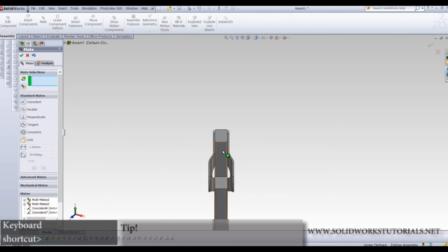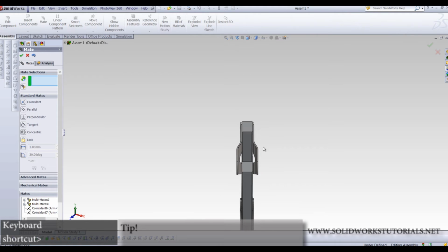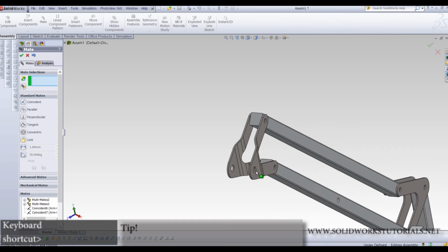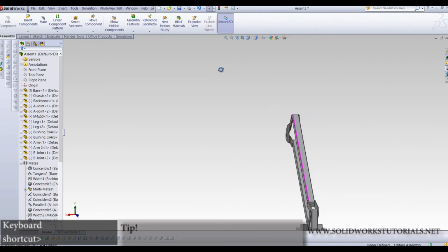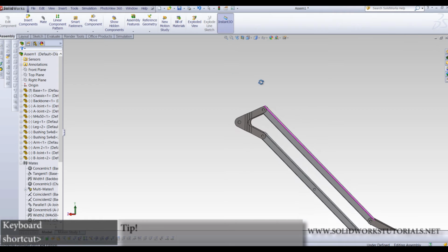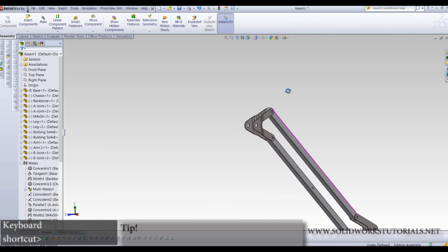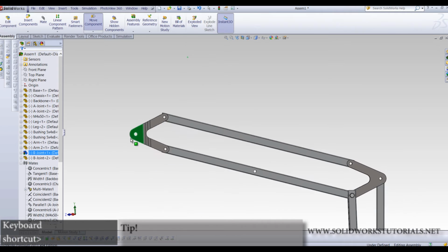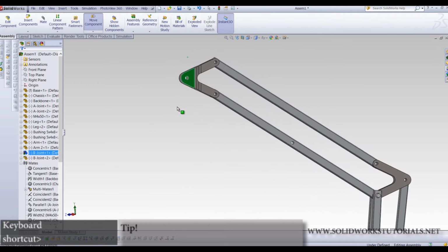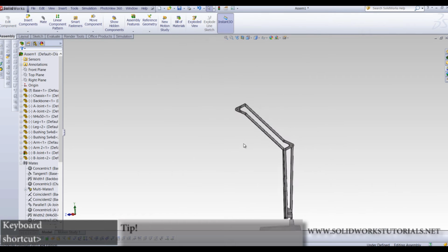You see what happened? The tighter part is connected to the upper arm, and the larger part is at your distal point. I'm going to rotate it a little bit so you can see what happened here. That should be the B joint, right? That's your B joint. You can definitely move it around, and you're not interfering with any other mates that you have created by now. So just leave it anywhere there. That's good.